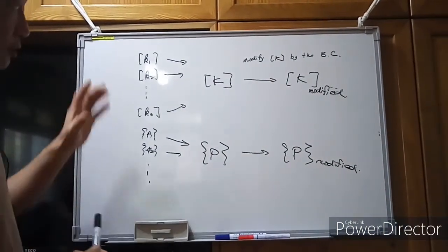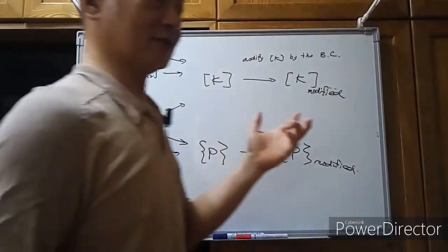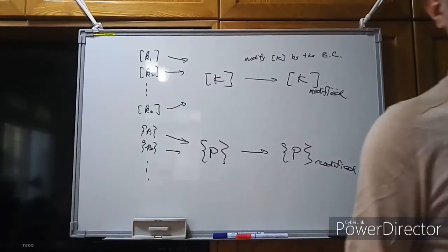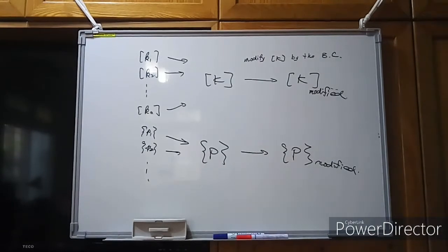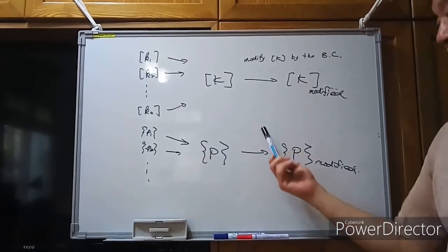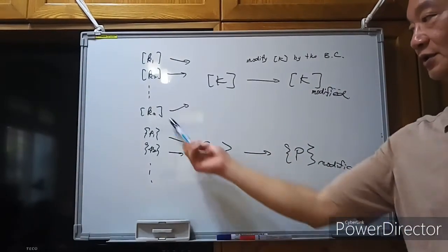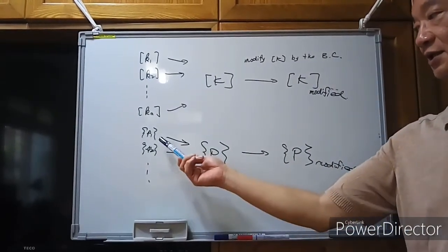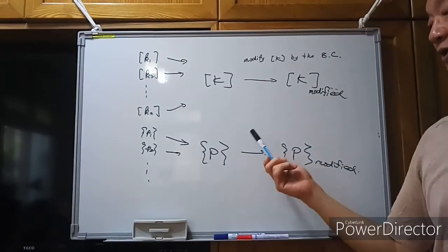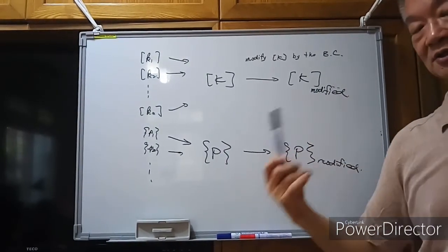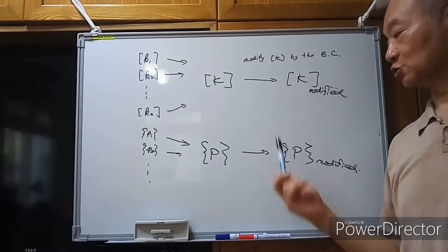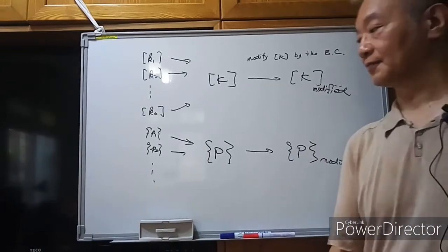So that's the procedure. We need to calculate all the element stiffness matrices, assemble them into the global K, and also calculate all the local load vectors and assemble them into the global P vector. And we can use some methods to modify both the K matrix and the P vector.